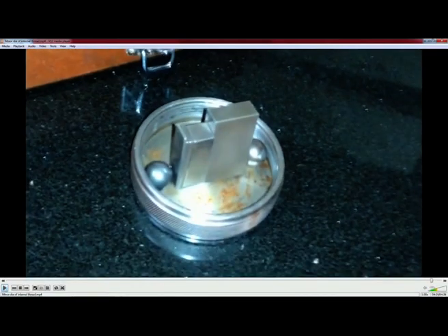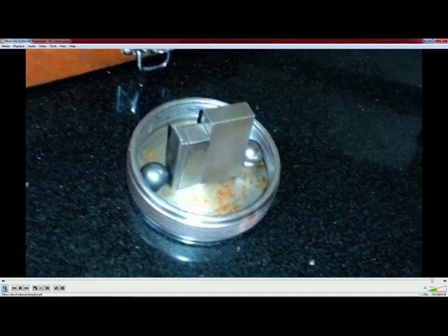Now, this is the width of the slip gauge assembly, that is 33.231 millimeter. The total width is 33.231 millimeter, and then we have to add the diameter of this steel ball and the diameter of this steel ball to get the minor diameter of internal thread.